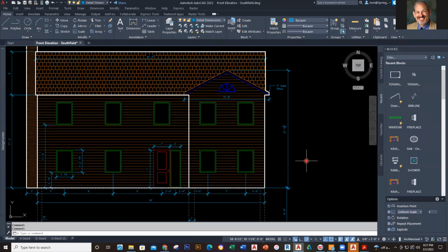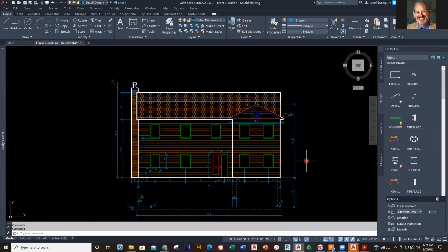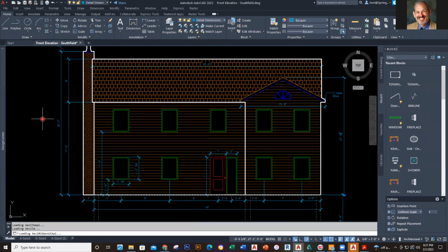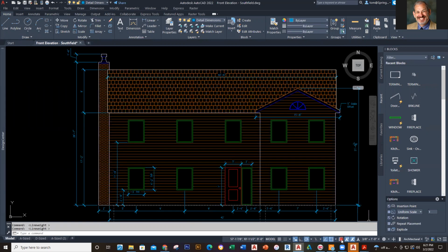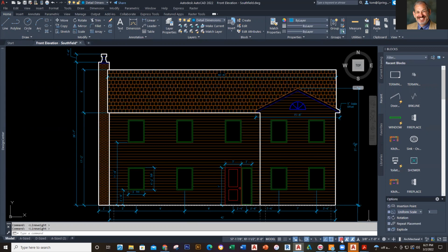You'll look at this and notice that it has the black background because we're in AutoCAD. Other than that, it's what we had seen before. And what you're going to see right here is an exterior line around the main aspects of it. That is a fairly typical convention. That is actually a thickened line. I can turn the line weight on and off down here, so I can see how that works. Turning that on gives a boldness to the actual projection of the structure. So I have that there, and this is what we're going to draw.